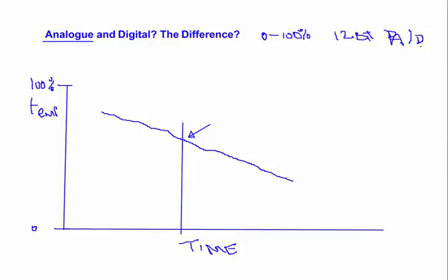No, you've actually chosen 8 bits. 12 bits, would you believe, is 4096. And that means that each increment represents 1 in 4096 parts, or 1/4096th of the range of the instrument.